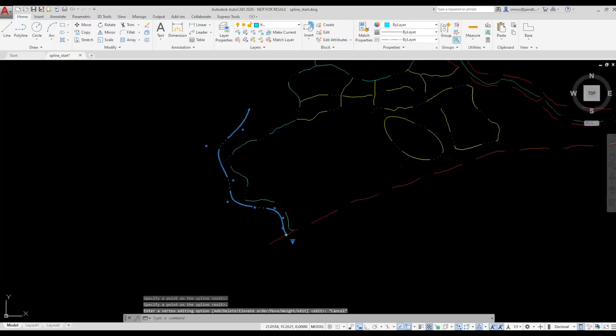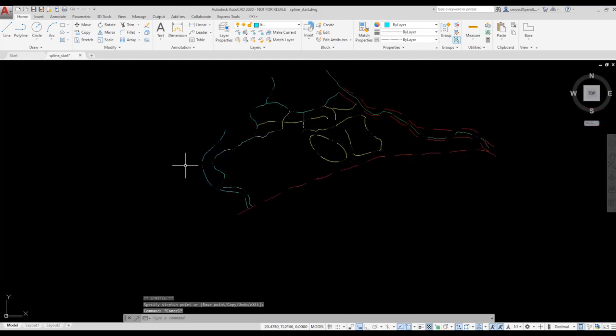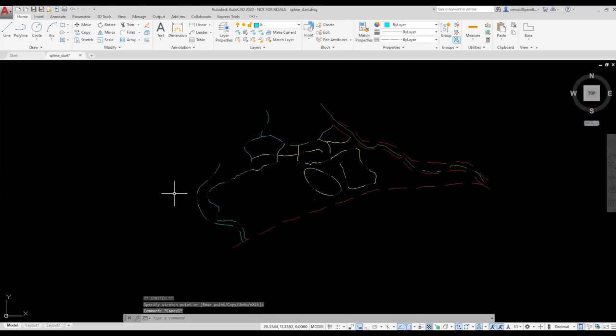Splines can have a major impact on your system resources. Because splines are composed of tiny line segments, they require an incredible number of calculations. This can slow down the performance of AutoCAD as well as your workstation. If you're noticing your system slowing down, you can convert your splines to polylines and regain the lost performance.